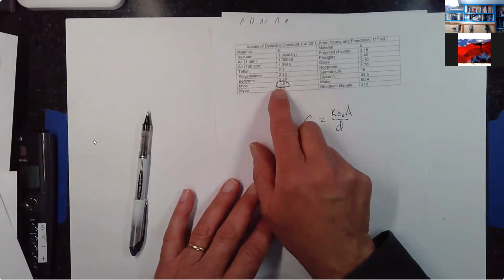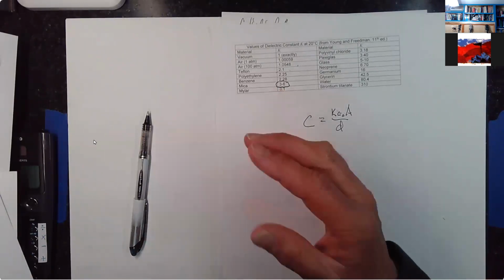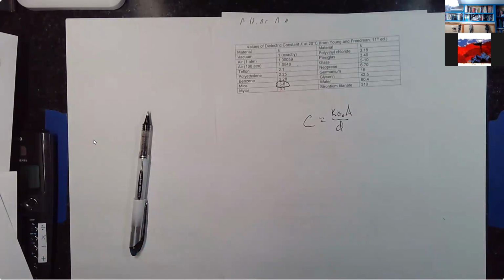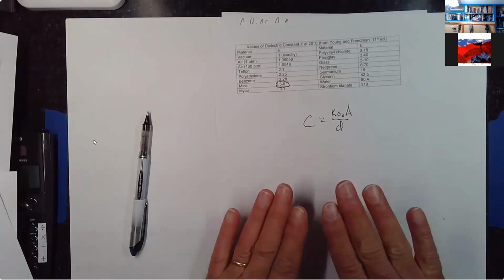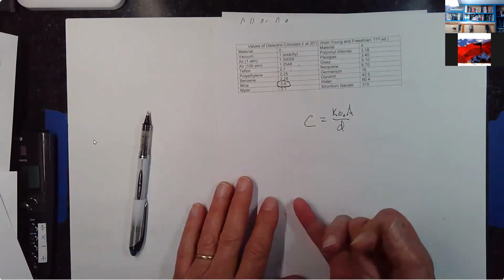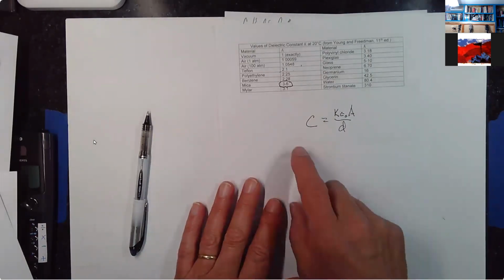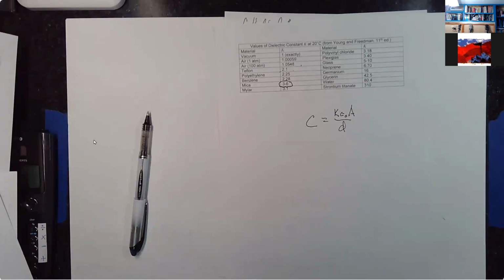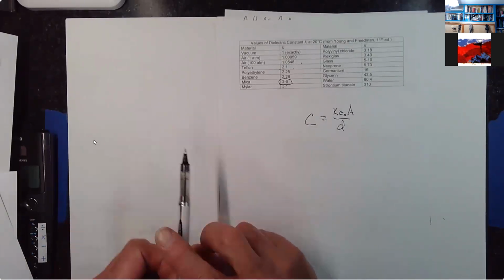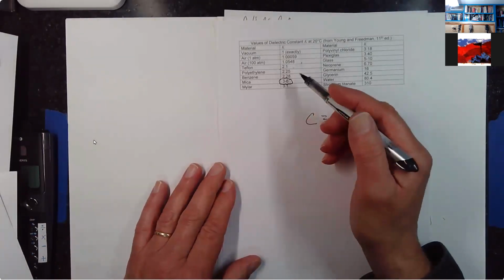And if you see mica, it's kind of a shiny looking thing in there, and it has the property that it forms a crystal with very thin sheets, and you can slice those sheets out and use it for a dielectric in a capacitor. That was something that used to be used. It's not so easy to work with, but they did anyway. Teflon's a whole lot easier to work with than some of these plastics too.